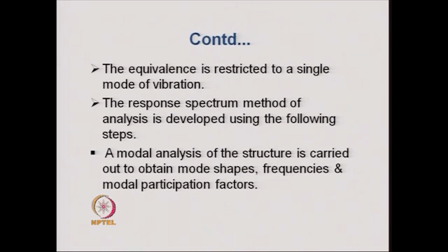The response spectrum method of analysis is developed using the following steps. First, a modal analysis of the structure is carried out to obtain mode shapes, frequencies and modal participation factor. All of you have done this exercise when you have undergone a course in dynamic analysis of structures.